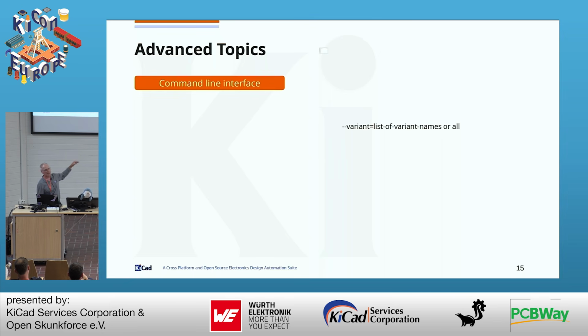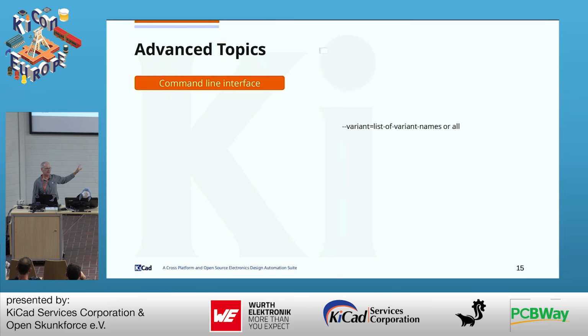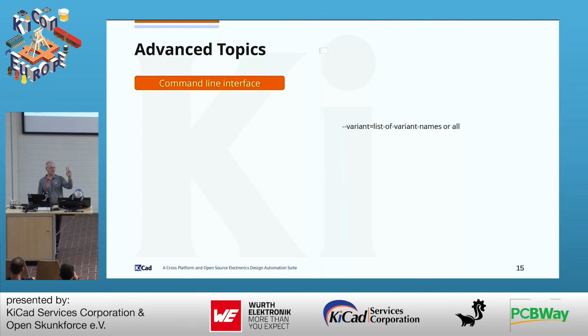Right now, the way it's set up, at least for these, it will suffix the name of the variant, or append it onto the end of the file name. So you'll get project, variant name, whatever file format, CSV or whatever file format you want the BOMs in. This also applies to all of the other outputs where variants matter: PDFs, anything where the information on the export would change.